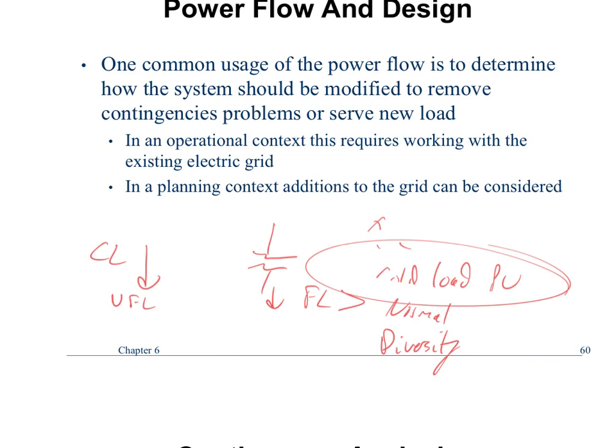Their protection protocols are probably mostly bypassed because that's an emergency condition. So they probably just said the generator breaker is closed and we're not going to trip it unless we have a super critical condition, with somebody standing there with a push button, ready to go. Because at that point, you can't protect the generator. You just have to hope that you can get online.